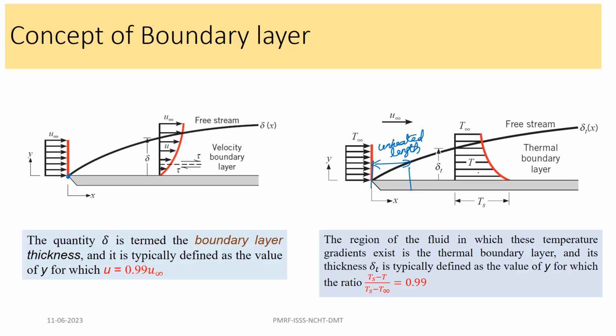You can see this boundary layer here. You should never indicate an arrow like this because it's not a vector quantity, it's a temperature. So just show that TS. You can see that there are different gradients here. T infinity, and you can see this TS is greater than T infinity, right? Because the length of the line is actually bigger, TS. So this is a heated plate. If it was a cold plate, it would be lesser and would finally increase to a larger outer value. So this will be T infinity and this will be TS.